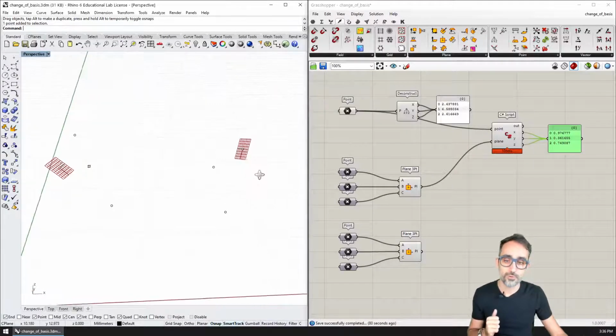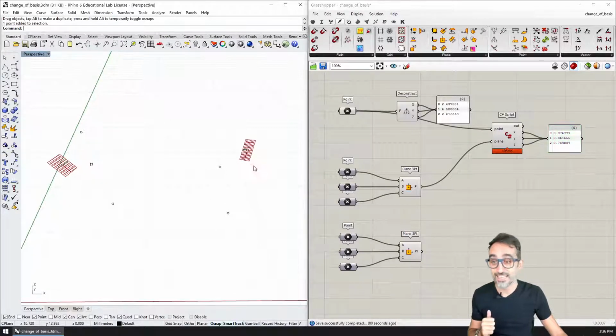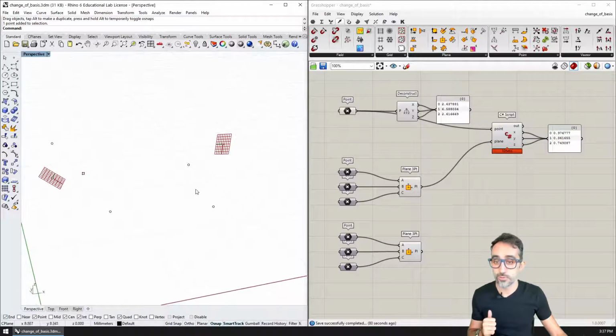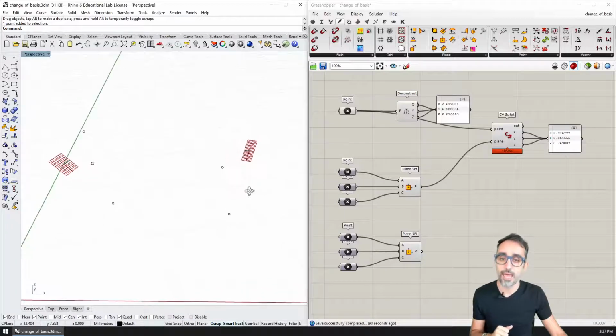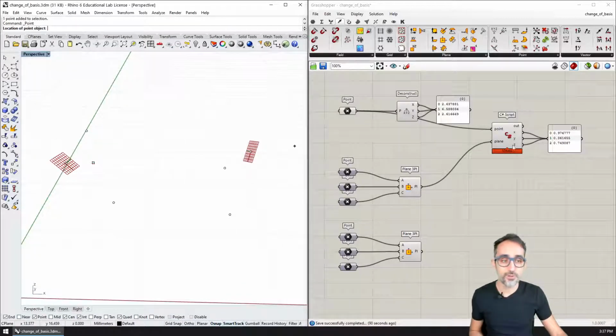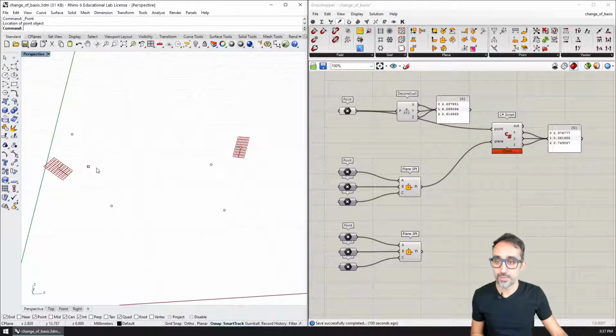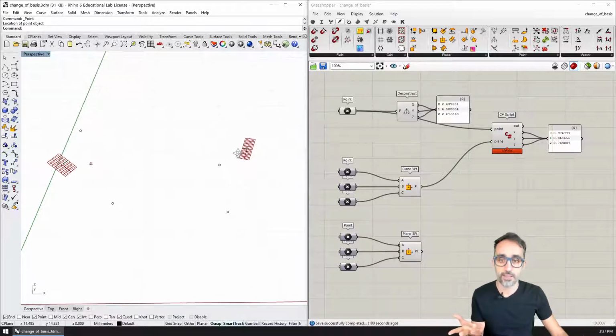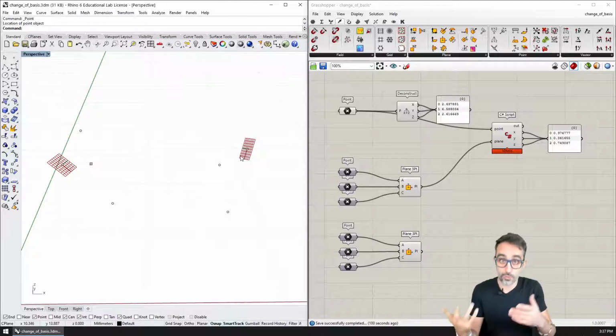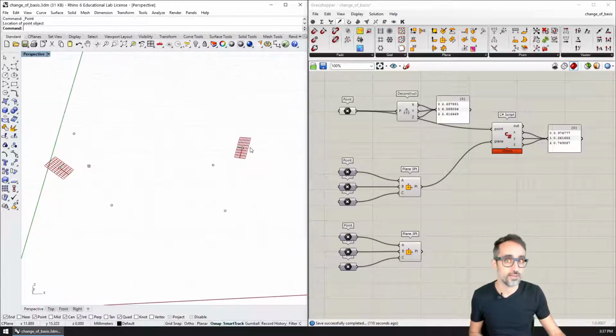What I have done is create a second plane, also from 3 points, using functionality available in Grasshopper. Then I'm going to extend this exercise so that I can generate a new point at the same local coordinates in this new coordinate system as this point is in this plane. I would like to find what the world coordinates of that point are in this new reference frame.